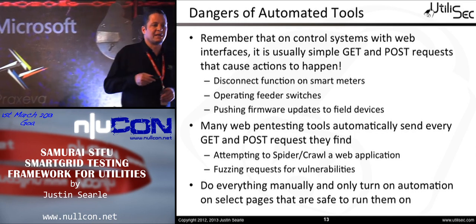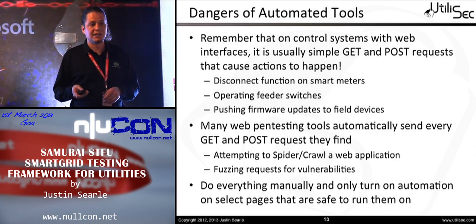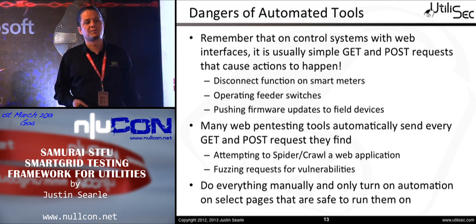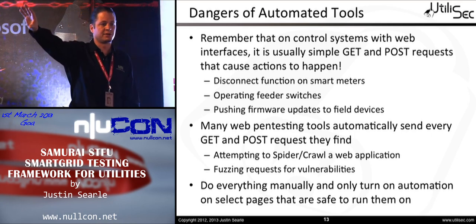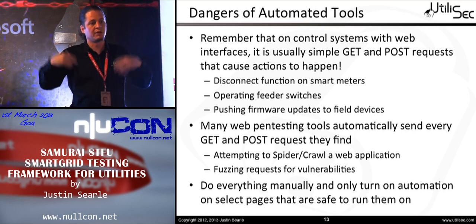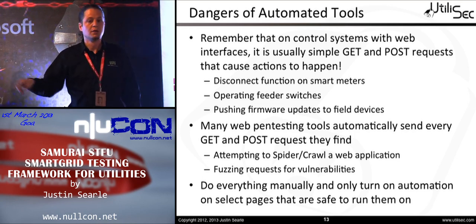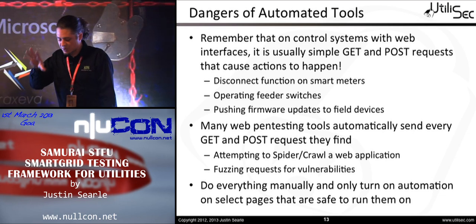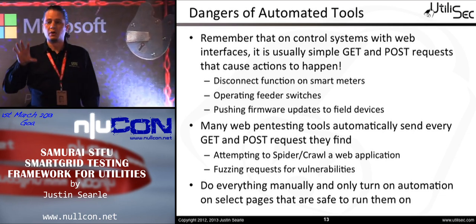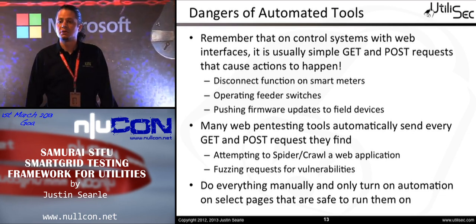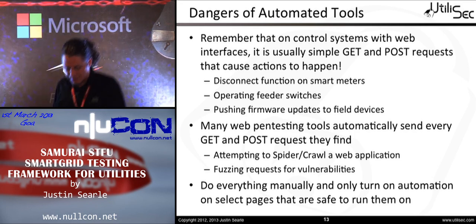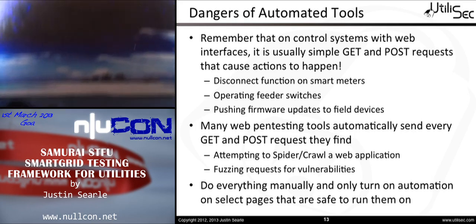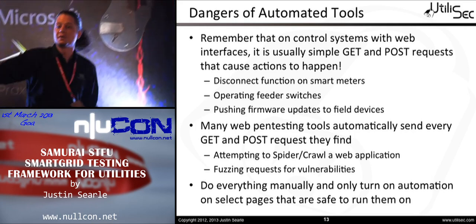However, as web pen testers, if you go through and use your normal routines and you kick off your spiders to go start spidering, you kick off your automated vulnerability scanners to find the vulnerabilities so you can start looking and reading those while you're doing your manual pen testing, you'll crash all those systems. Okay? The problem is, on a control system network, the control servers where we have these web interfaces, in order to shut down power for a substation, usually is inside of a web page where we actually have a form where you specify the change that you want to make and you hit submit.